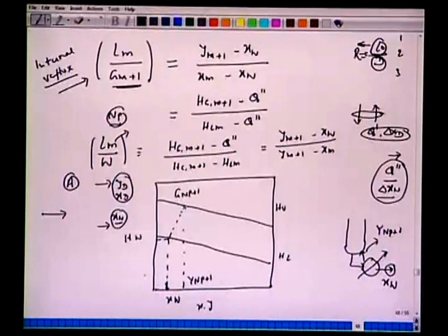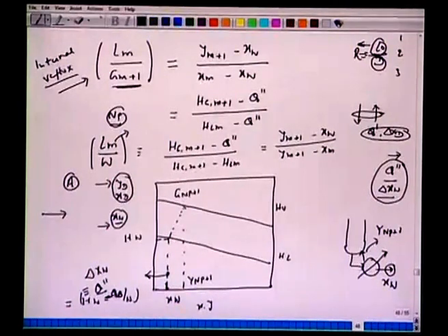And on this x_W, the more important is now your difference point delta x_W, or you have Q double prime. So, we have this Q double prime equivalent to H_W minus Q_B over W. So, this is a reboiler load equivalent to this Q_C which we had for the top column. So, we can mark this point here. Once we have marked this point, now it is easy to draw.